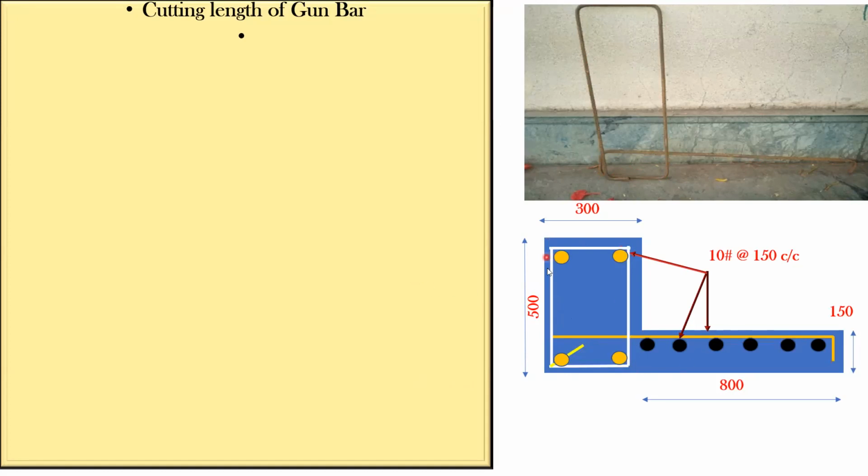So this is a beam what we have. The depth of the beam is 500. The width of the beam is 300. And the thickness of the Chajja, this is a cantilever, and thickness of the slab or thickness of a Chajja is 150 mm. I have written it here. And this is your top steel. This one here is your top steel. And the black color one is your distribution steel. And these are the stirrups for the beam.